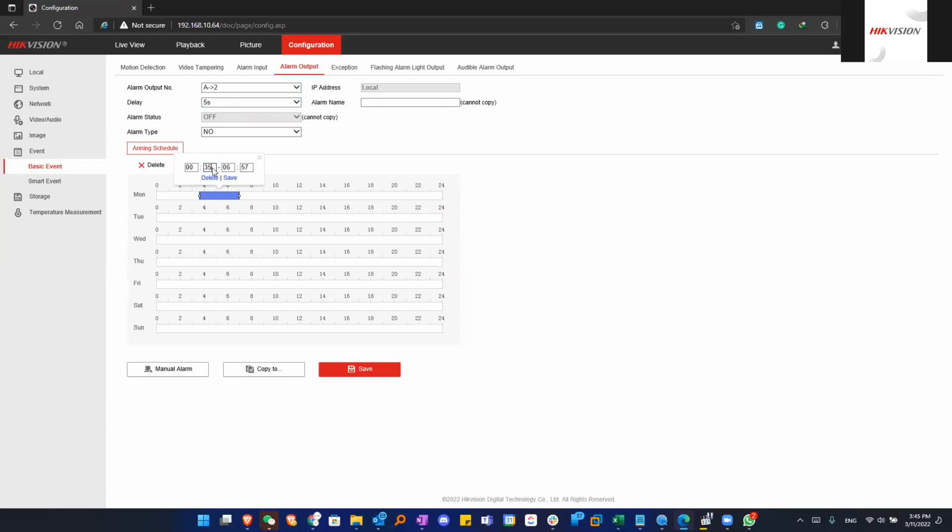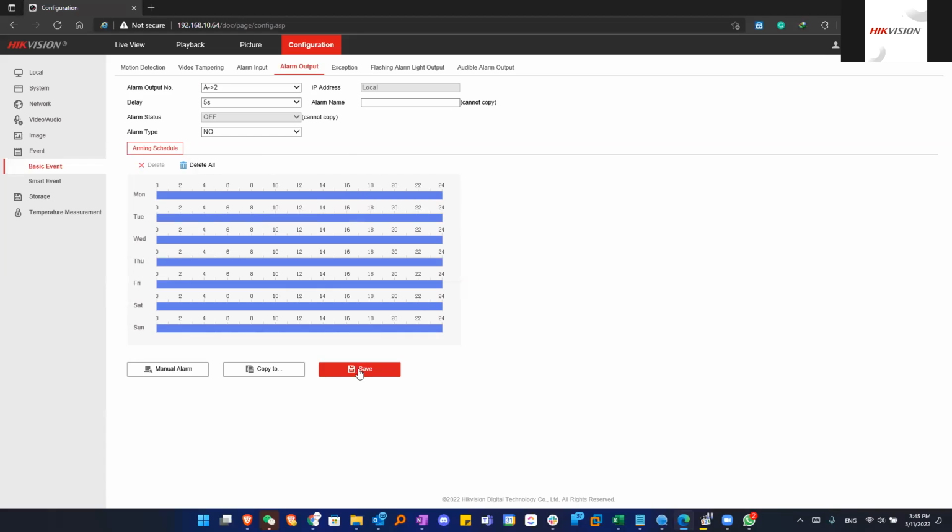So Taranju, now connecting a third party siren or, let's say, a strobe light should be pretty straightforward. Normally these things simply operate when you give 12 volt or 24 volt power. This output is working as a relay, but if you have an incompatible voltage rating, make sure to purchase another third party relay and run it through.